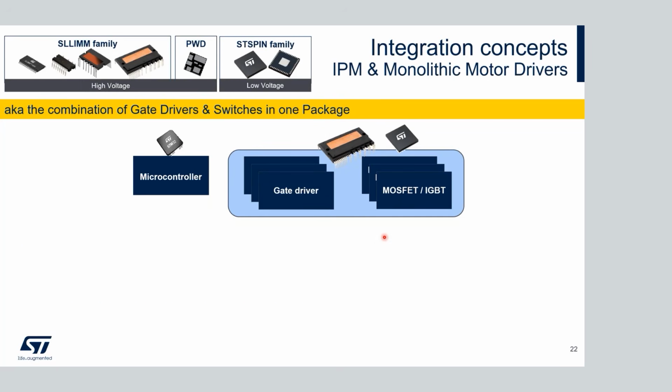Last but not least, the intelligent power module or monolithic motor drivers integration approach. We combine them here because the idea here is the same for monolithic motor drivers and for the intelligent power modules. It's the same idea. You integrate the driver, a logic for the monolithic motor drivers, a driving logic embedded, and also the power switches. So this gives you the integration of the entire power stage in terms of driving and switching.